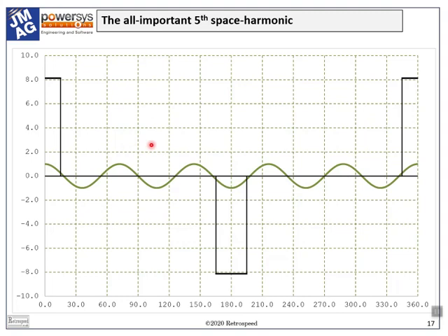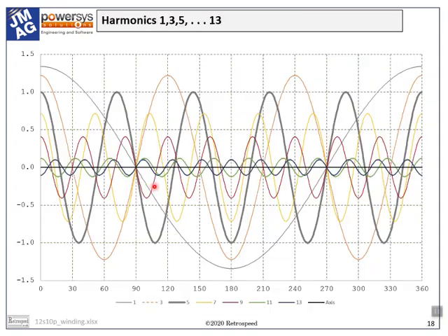And there is enough information here to take the design almost to completion, because it will give us the fifth harmonic winding factor, and that enables us to calculate the fundamental EMF and the torque constant. At the same time, we will be able to find the copper losses, which are related to the peak value of the rectangular MMF and not the fifth harmonic. Let's add a few more harmonics.